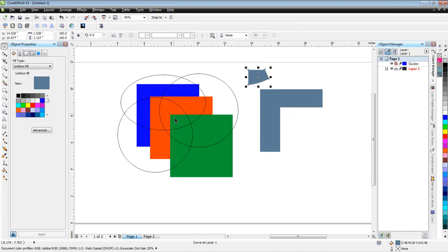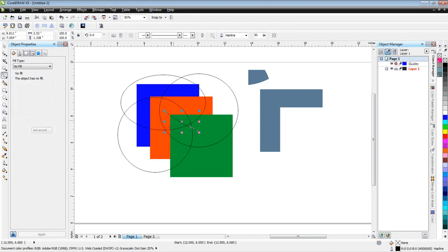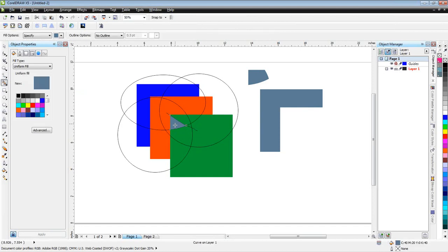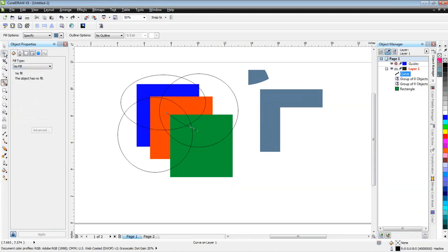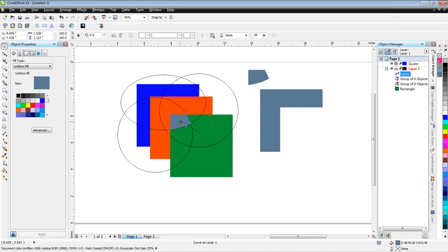Now that is enclosed objects. If one of these was an open object, we'll say we'll put a line across here. Since it's enclosed on both sides, this would work with the Smart Fill. What I mean by enclosed on both sides, it's finished there and it's finished here, so Smart Fill catches that portion there. So we'll hit Control-Z. And I'm going to edit this node. If that wasn't quite finished in there, what will happen with the Smart Fill is it will do a Smart Fill, but you notice it didn't cut off anything there because there was no boundary to stop it. So we end up getting a piece that's just like the one before.